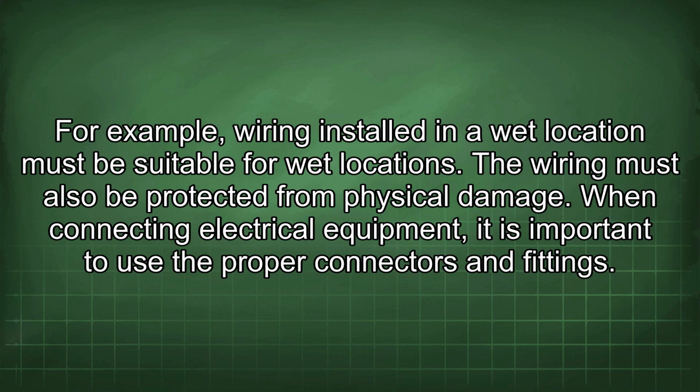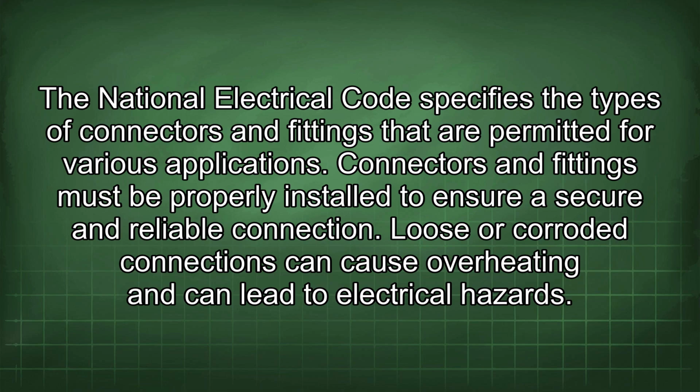When connecting electrical equipment, it is important to use the proper connectors and fittings. The National Electrical Code specifies the types of connectors and fittings that are permitted for various applications. Connectors and fittings must be properly installed to ensure a secure and reliable connection. Loose or corroded connections can cause overheating and can lead to electrical hazards.